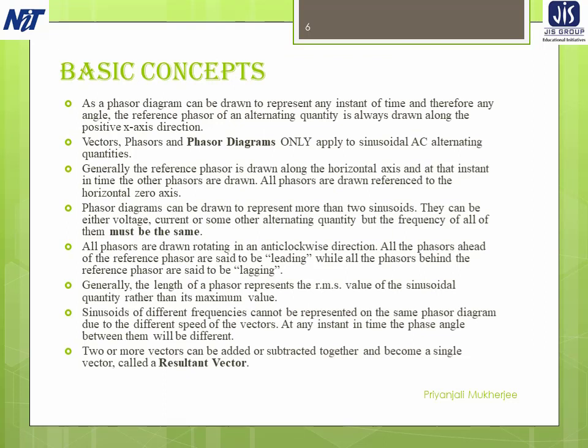As the phasor diagram can be drawn to represent any instant of time, therefore the reference phasor of an alternating quantity is always drawn along the positive axis. And vectors, phasors or phasor diagrams are only applicable for sinusoidal AC alternating quantities. All the phasors are drawn from the reference, that is the horizontal zero axis, and phasor diagrams can be drawn to represent more than two sinusoids.